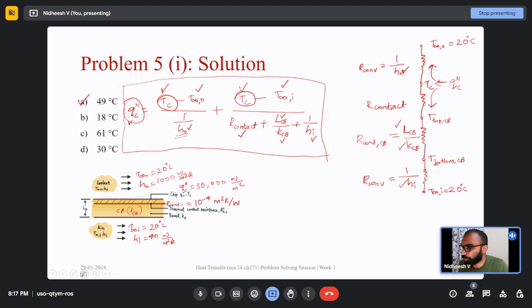No. See what is happening. The total heat that is generated is Q. Heat flux generated is QC. This portion is at a higher temperature compared to this point. Say I'm calling it point 1, and I'm calling the bottom point 2, and the chip I'm calling point C. Point C is the source of heat. It is at a higher temperature. So heat is flowing from both PC to P1 and from PC to P2.